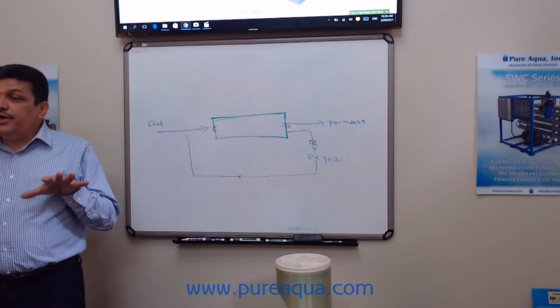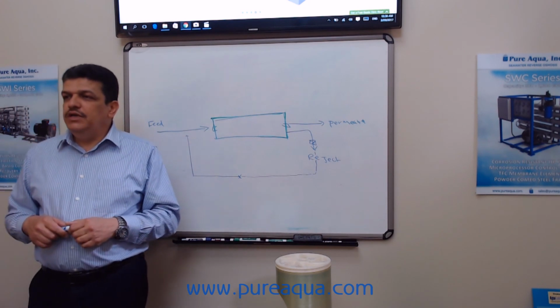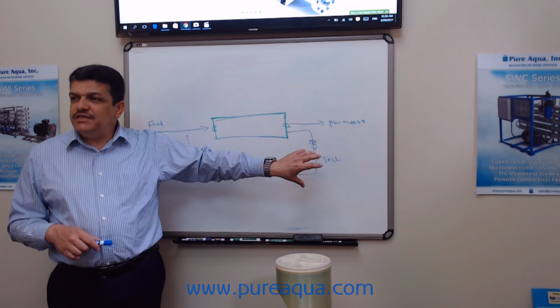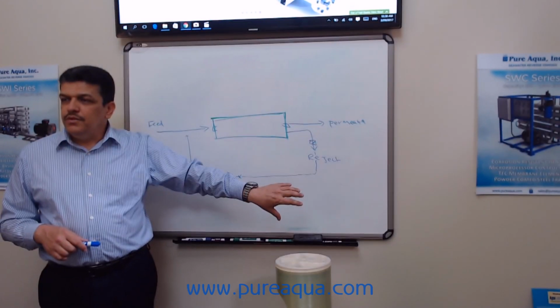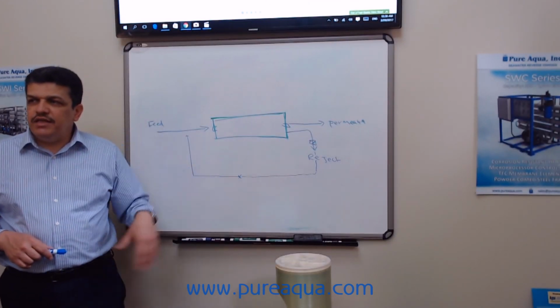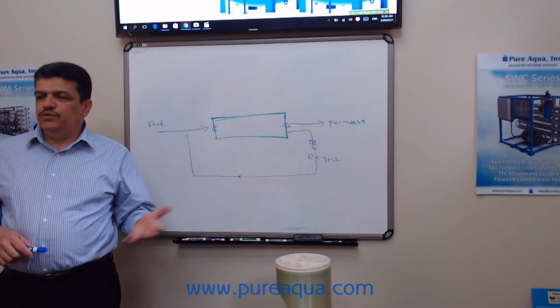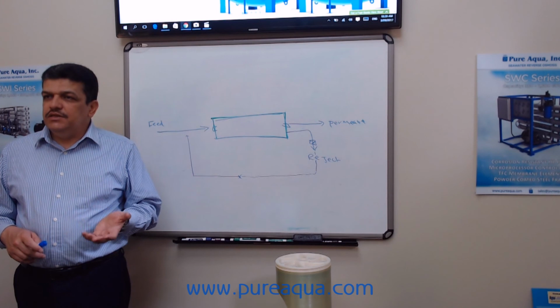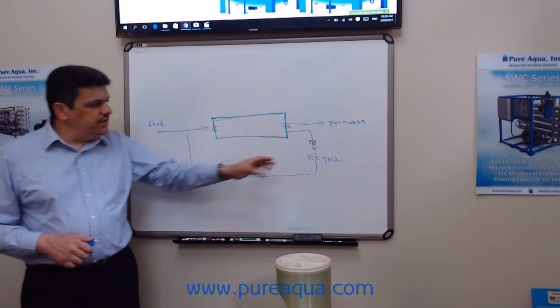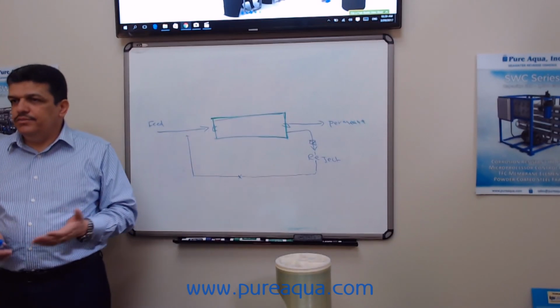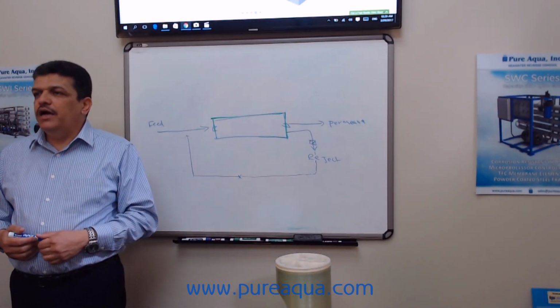Now, in some countries, the water is really, really scarce. Taking this water and passing it through another RO to minimize the wastewater that's going to go to the sewage network, or back to the sea or whatever, is feasible. Treating this water is for sure going to be way cheaper than treating seawater because seawater has way higher salinity.